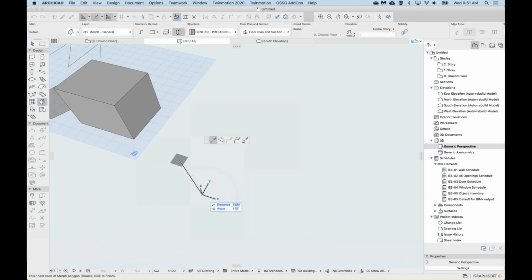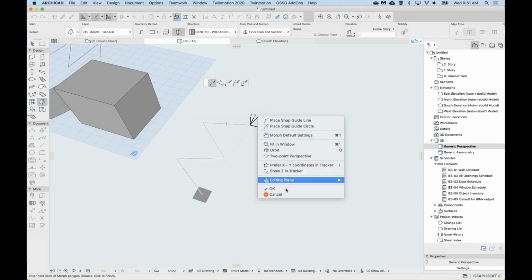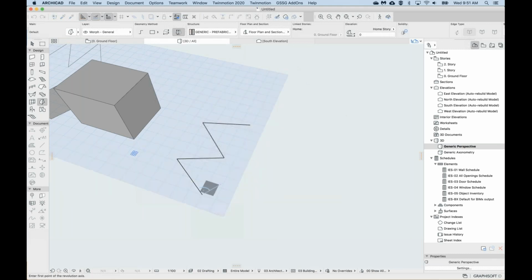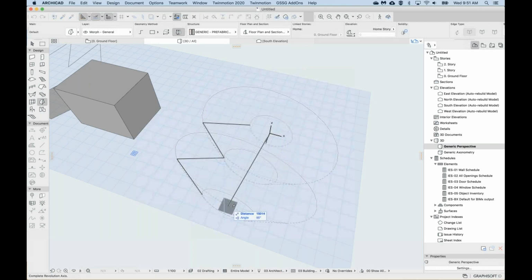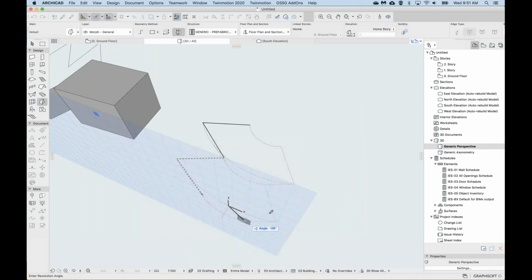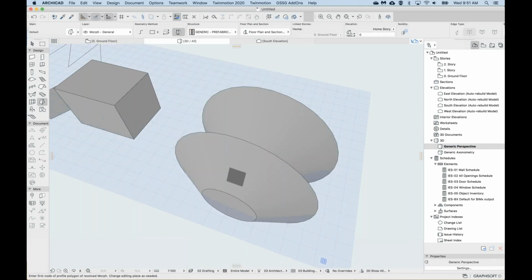Okay, so once you've finished the M polyline, you just need to right click and OK to finish the polyline. So it turns to a bold black. And then you need 2 clicks to indicate the axis, where that M is going to be revolved around. And once I do 2 clicks, I can just enter the value 360, and that will make it a full revolution.